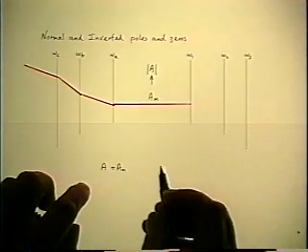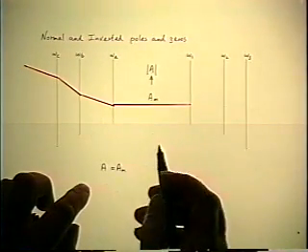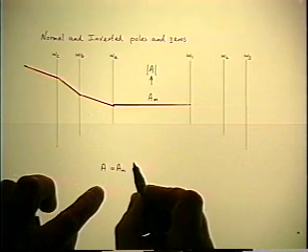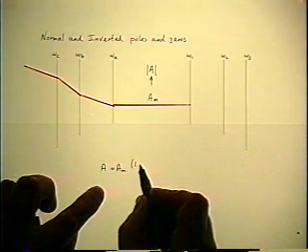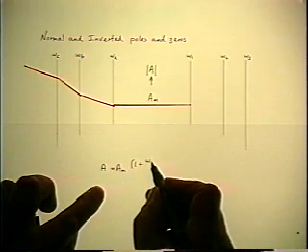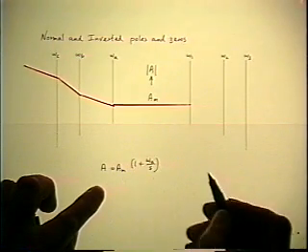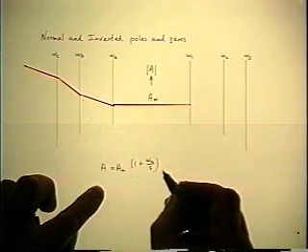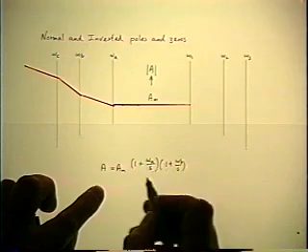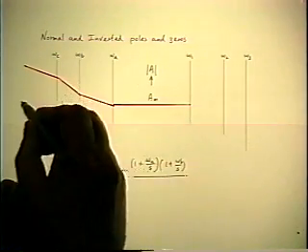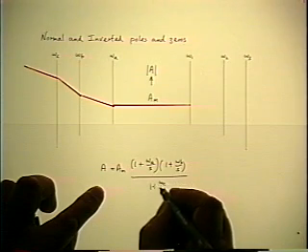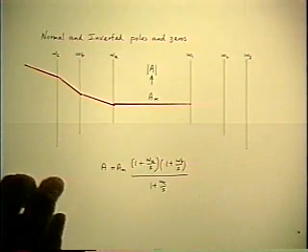Okay, let's look at that. Just ask those two questions sequentially. If you look down from AM, you see a concave upwards corner, so it must be a numerator factor, but you're going down in frequency, so it's an inverted zero at omega A. Omega B is the same thing again. And finally, it bends downward, so it's a denominator factor, and you're still going down in frequency, so it's an inverted pole.